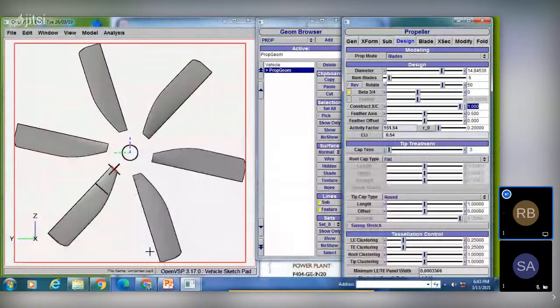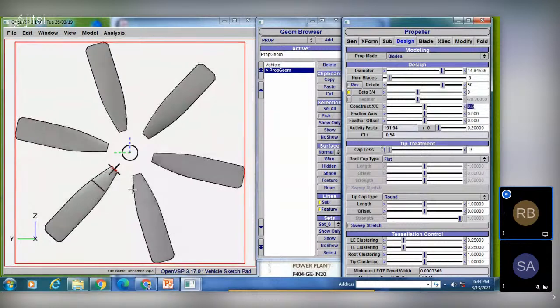And the opposite of that part, that is the trailing edge, is not flat, or it's not straight. So to maintain the symmetry, what we have to do, instead of 1, just type 0.5, and you can see symmetry.